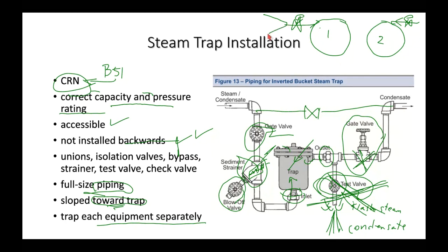So maybe this one here has got a lot of steam going in it because the load on this exchanger is high, and so it's using a lot of steam. And maybe this same one here at the same time has a low load. It's a heat exchanger that serves a different system. But because this one here is under a low load, it's not getting much steam at all. So can we save money by hooking them up together and using a single steam trap?